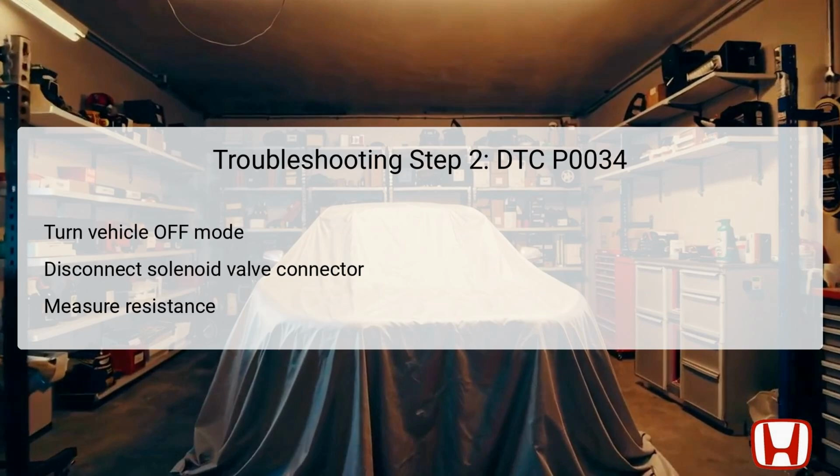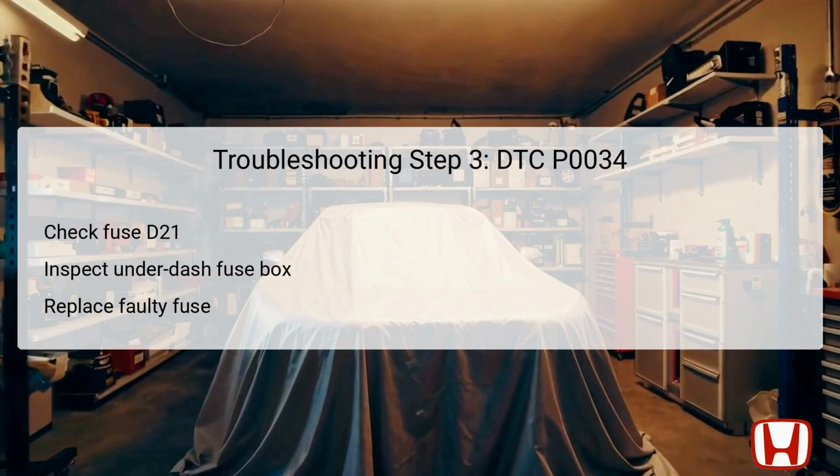However, if the resistance deviates from this range, immediate replacement of the solenoid valve is necessary to resolve the low voltage issue. Next in the troubleshooting sequence is a critical check of fuse D21, which is located in the under-dash fuse/relay box. This fuse plays a vital role in protecting multiple electrical components associated with the turbocharger bypass control solenoid valve.